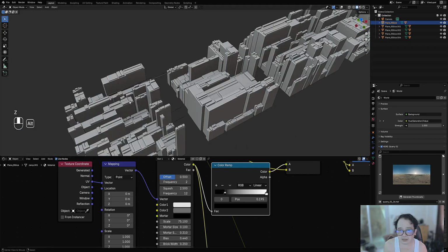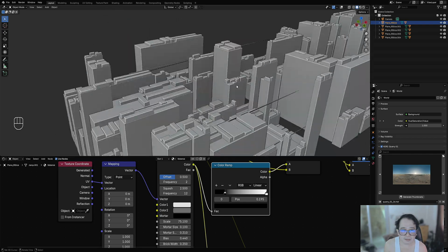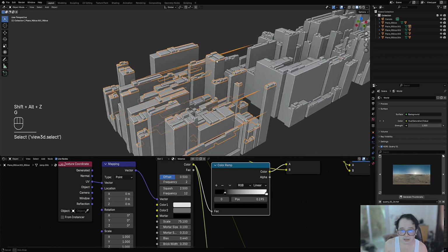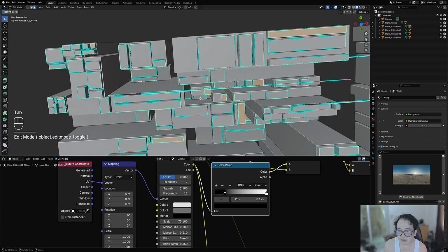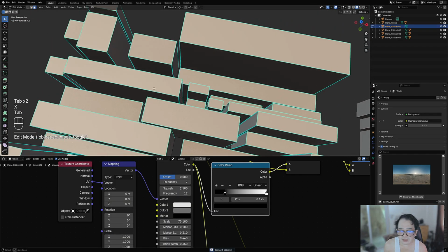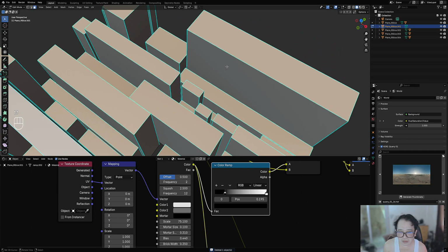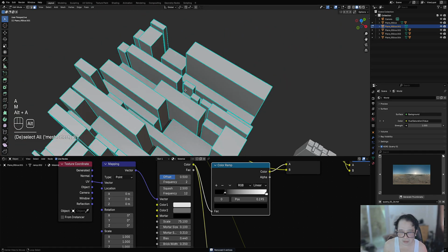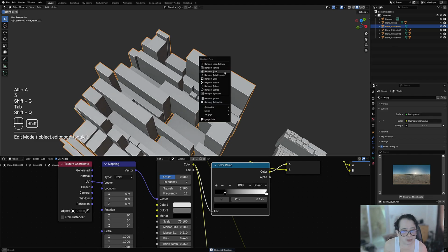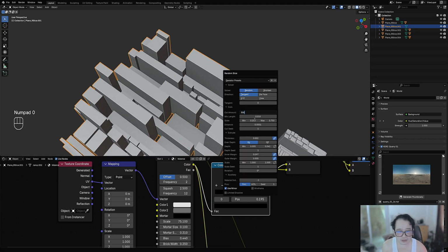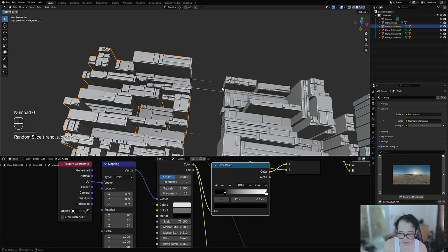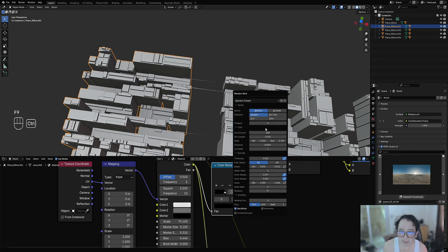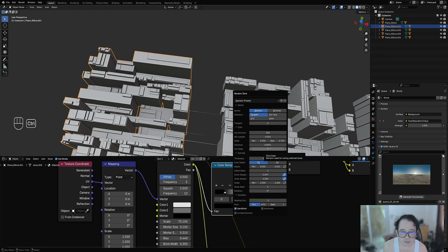Okay, there's spiking here. And this is because of the margin probably. And so let's delete this. Let's actually make sure that there's no doubles. Okay, Shift G, normal. So let's just repeat the iteration or the randomization and use random seed to get rid of the spiking. Spiking is probably from the inner margin or even from the thickness.